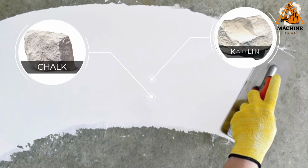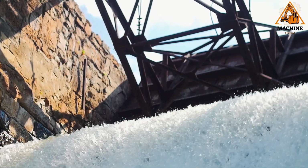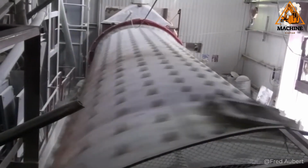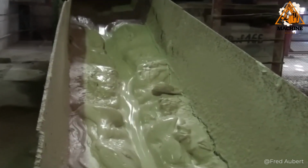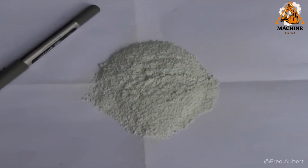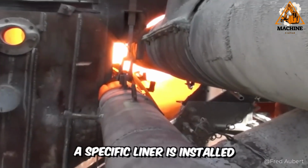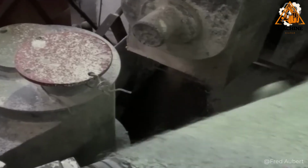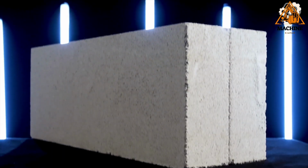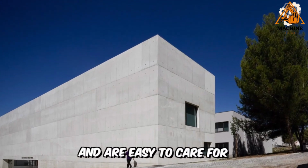For the whitish color, the chalk and kaolin in the composition are responsible. Not insignificant in this production is the very quality of the water used. The material undergoes several levels of purification, so the result is cement of high quality. The grinding of clinker continues in the mill unit, in which a specific liner is installed. The grinding delicacy of white cement is much higher than that of ordinary gray cement. As a result, white cement products do not crumble, do not deteriorate, and are easy to care for.